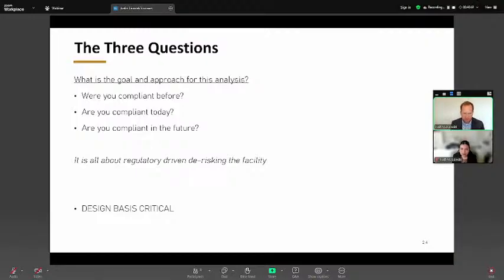And all of this CVS is very much, from a regulatory standpoint, based upon risk mitigation. But even in practice, we're de-risking the chance of venting. We're never going to be able to prove, or control exactly, what's going into the tanks. We're never going to actually model in a reasonable manner what's going to the tank, what the flash is coming out, what the product coming out of the ground is, or that it's consistent from month 1 to month 2.